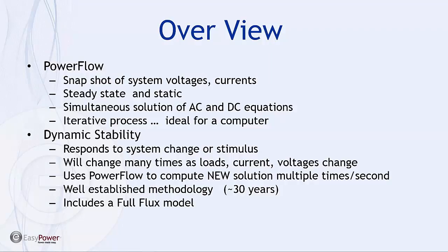Very frequently when we do an arc flash study and a customer has the ability to record or take down the voltage and current readings in certain parts of the system, we will do a load flow study, at least a partial one, as a means of error correction or verifying that the data collection process was as accurate as possible.